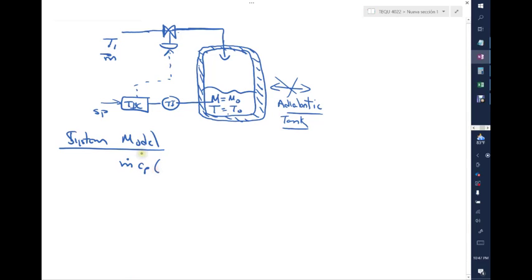Now remember, this is an energy term that needs to be taken relative to a given reference. So it actually is T1 minus T reference. We're going to talk about the reference at a later time, but for now let's say that this is the flow of energy getting in. We multiply that by delta T, a small amount of time. Since it's adiabatic, I don't have to worry about anything else, except that this has to be equal to the change of energy inside here.